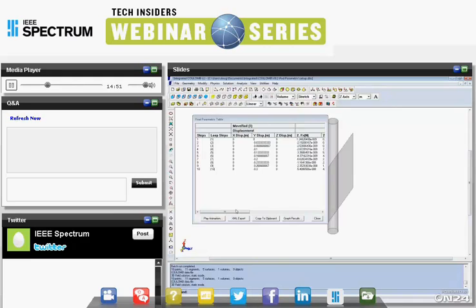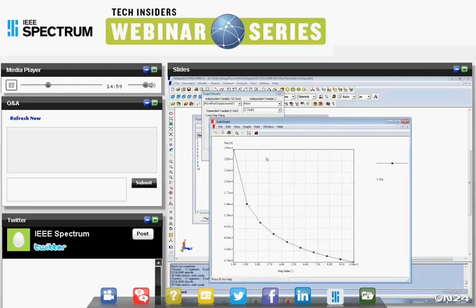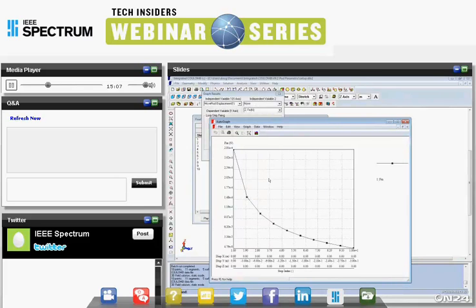And now I have my data table, which lets me create plots such as force magnitude versus position. So now I have a plot which says as I move the rod, the force is getting smaller and smaller. And if I turn on auxiliary axes, I can verify the displacement in terms of how far it's moved according to the X, Y, and Z locations.